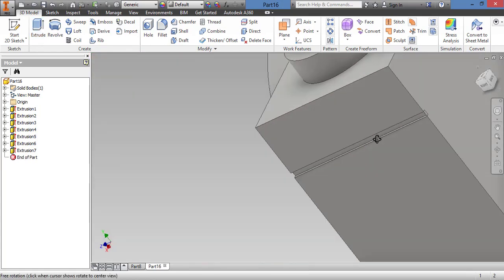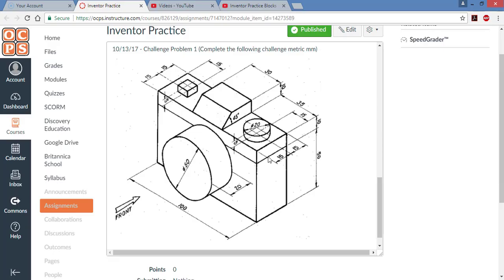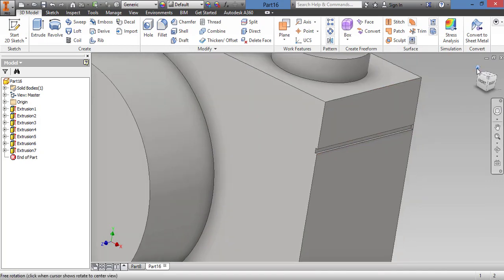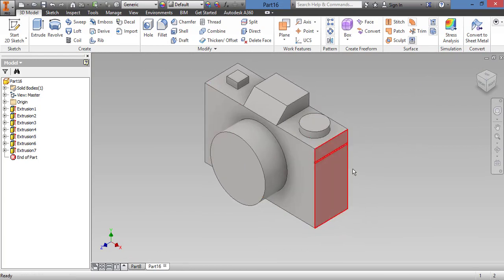And I would suggest cutting like 0.5 or something small and hit OK. And you can do that all the way around the entire object lined up so that you get this little division point. For those of you that aren't as comfortable with the program, you don't have to do this, but it is something that's pretty simple to do. So I would advise at least attempting to do this, because things will just get more challenging as we continue. So I'm going to go ahead and undo that step.